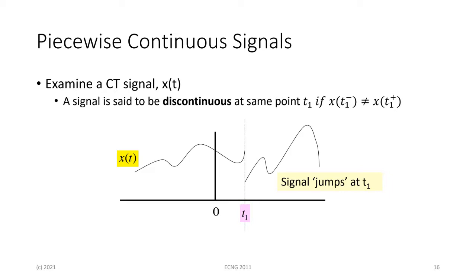Occasionally, however, things can happen. So for instance, if you have a circuit on your breadboard, and one of the jumpers that is carrying information, let's say you're measuring room temperature, is not properly inserted into the breadboard, what happens is that you're measuring a nice signal coming in, and then the wire shakes. So you lose the signal, and then the signal reconnects again.